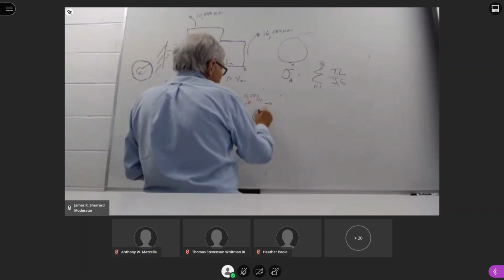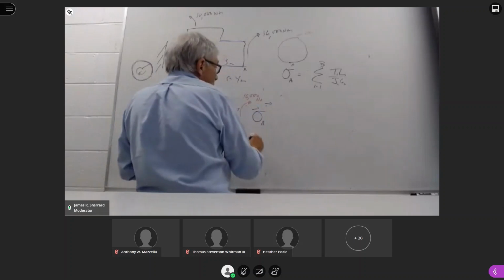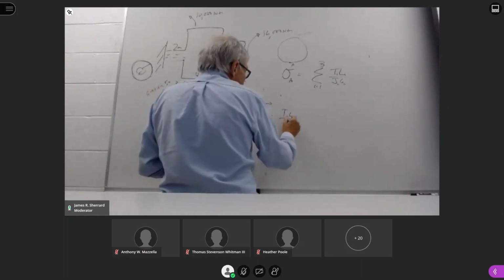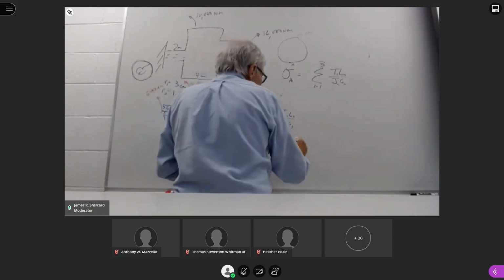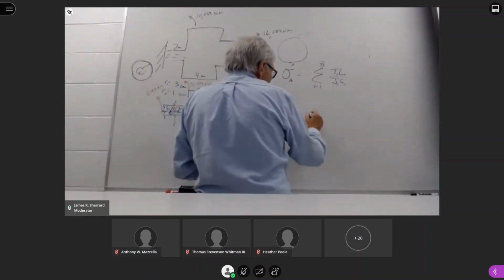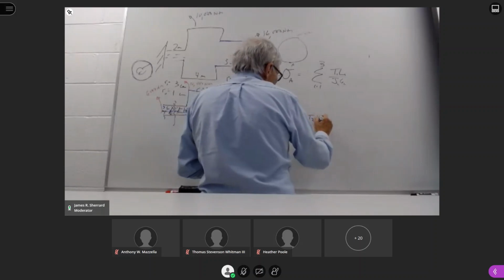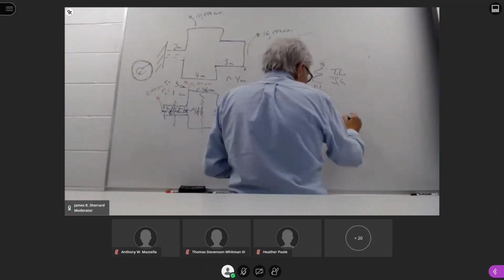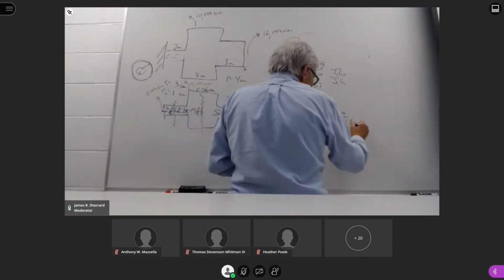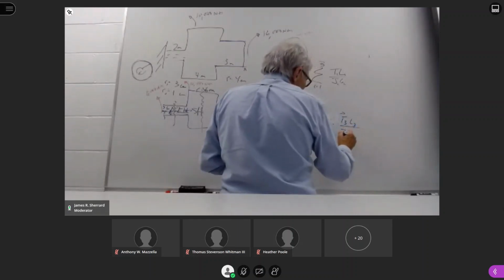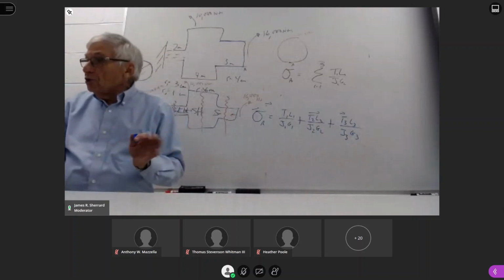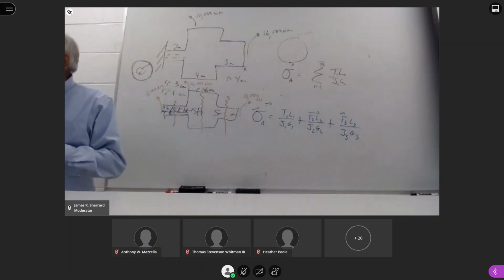So phi A, vector quantity, is going to be the sum of T1 L1 over J1 G1 plus T2 L2 over J2 G2 plus T3 L3 over J3 G3. Any questions on what I've done so far? Okay.